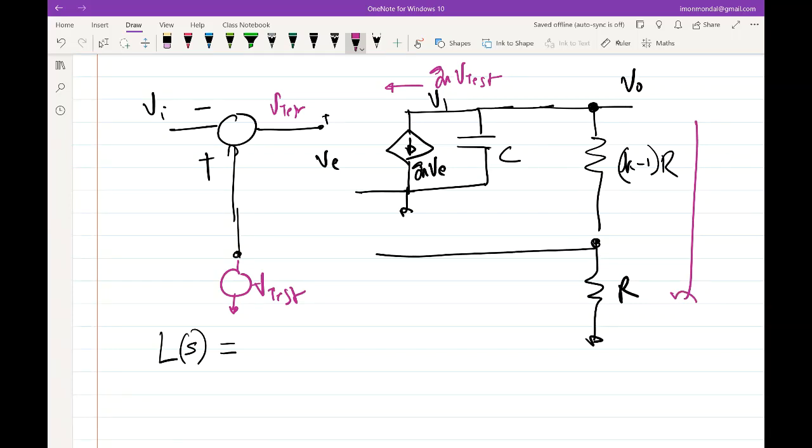That's why I saw many of you didn't actually physically break the loop. So physically break the loop to do the loop gain analysis. Otherwise, there can be misinterpretations of many things. It doesn't take much, right? So redraw it, break it, and then figure out what it is that is different.